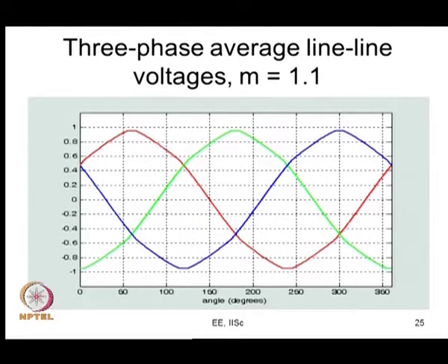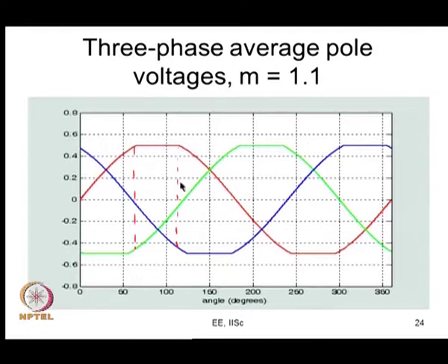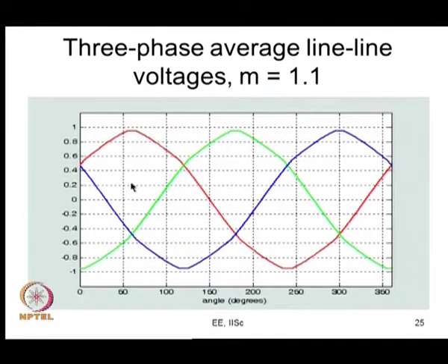Now, the procedure is clear, I have already delineated the procedure. So, when I subtract that, what happens now? Now, you look at these, they are sinusoidal voltages now. So, what has happened between the earlier waveform and now? Whatever the harmonic components were, the triplen ones have got knocked off, they have been removed, and all the other components like 1st, 5th, 7th, 11th, 13th etc. get multiplied by a factor of root 3 and they are here. If you do a harmonic analysis of this, you will find fundamental, 5th, 7th, 11th, 13th etc., and these harmonic amplitudes will be root 3 times the corresponding amplitudes for VRO average etc. So, you have your signal like this.